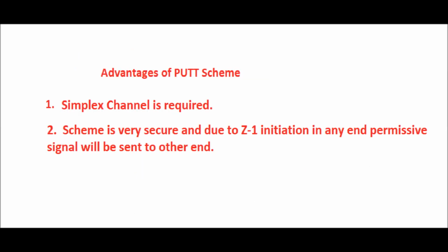So the advantages of the PUTT scheme: one simplex channel is required for permissive signal receive and send. This scheme is very secure, and due to zone 1 initiation, at any end a permissive signal will be sent to the other end.